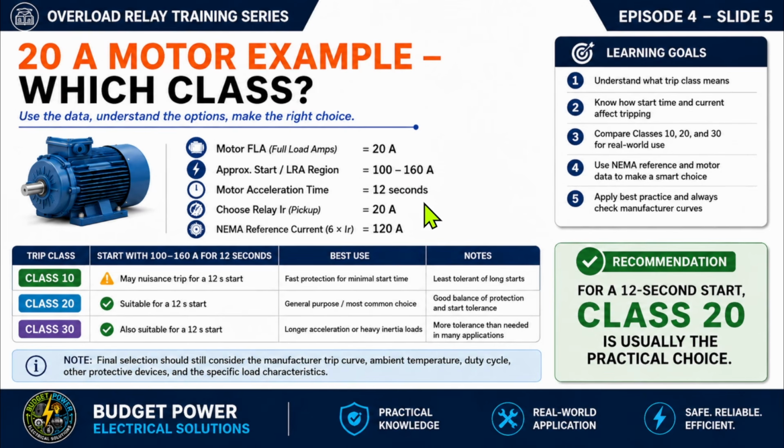And notice something important. We're not choosing Class 20 because the motor is 20 amps. We're considering how long the motor takes to start and what type of load it's driving.